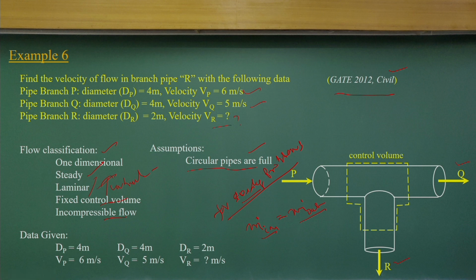So, in this case, because there are two outlets, the sum of these two mass outflows going out equals the mass influx, the mass flux rate coming in, the mass per unit time. So, a very simple way: rho Q in will be rho Q1 out plus Q2 out. That is the basic concept.